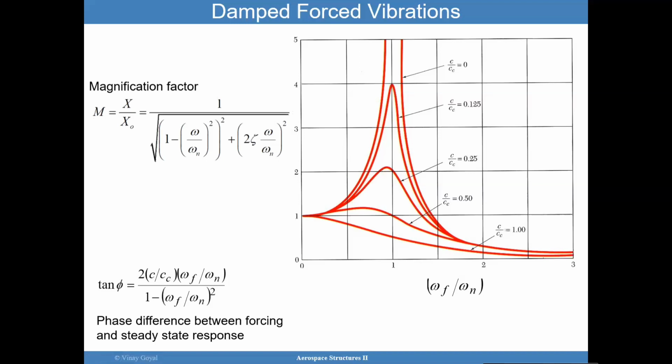And so if I were to apply the loading statically, I'll be overly loading the system. While in fact, if I apply the same load with a frequency that's much higher than the natural frequency, the system will hardly move. And so it's important to understand that this kind of chart can help you understand the response of a system. It can help you also design for it.